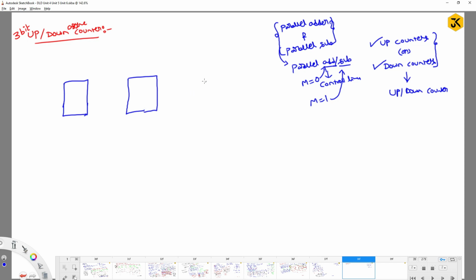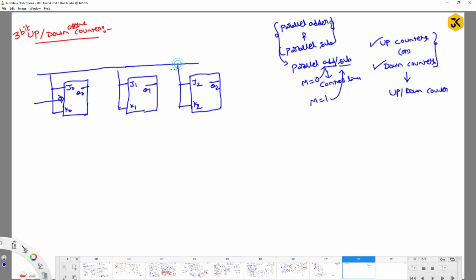So I am going to take flip-flops, with J0, K0, J1, K1, J2 and K2, producing Q2, Q1 and Q0, and as usual I apply negative edge triggering. For all of these we pass the toggle operation. For the value of J and K as 1, it is going to perform toggle, right?